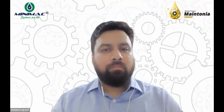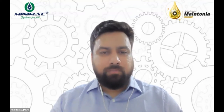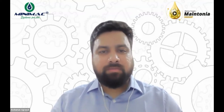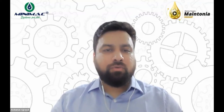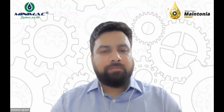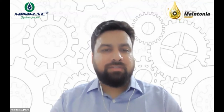These are helpful mostly in the case of steam turbine lube oil system and not in the case of control fluid system. So both the tanks, as Mr. Yogesh suggested, in the modern turbines, both the tanks are separate. One tank is for lubrication purpose and one tank is for the control system purpose. While we are doing the maintenance of the lubrication system, the chances of free water entering it are high because they have the cooler system where the leakages can happen. We have the steam gland seal failures which can happen. So all of these are sources of free water.